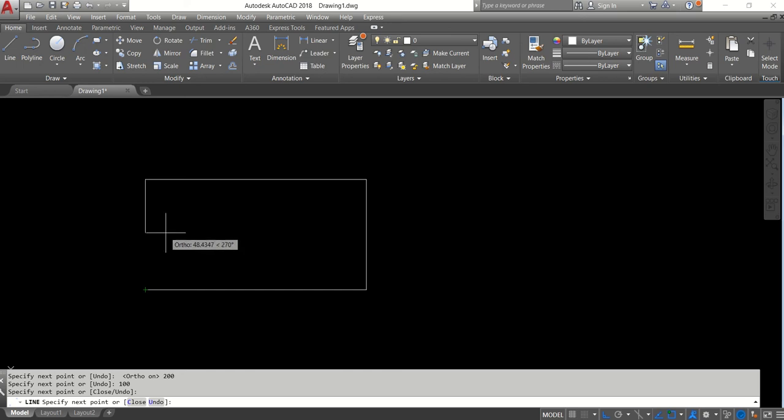Right. So similar thing, say I want to have a line in between this, right? Like maybe I know the distance 100, then the midpoint would be around, I would say 50. Okay. But if I don't know the distance, I can again use a tracking command. I can just bring my cursor down and I can reach the midpoint of this particular line, and if I come back it will exactly draw the line at the midpoint, and I can just click. Similarly again, if I want to come back on this, I will select the midpoint of this line. I'll move my mouse a bit up, and I'll just click the point and I'll hit the space bar. So that is how it has created the line command.